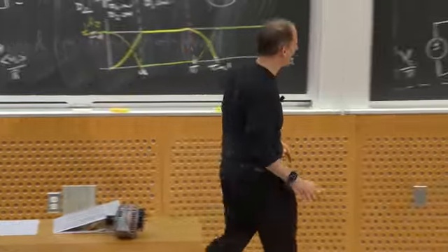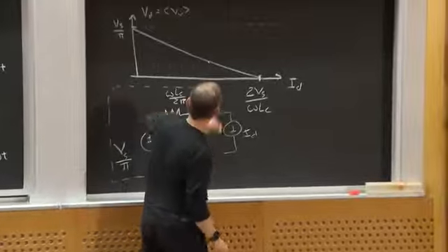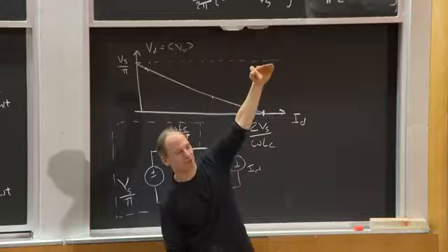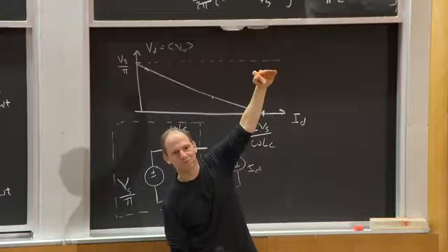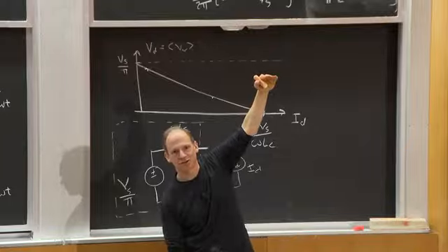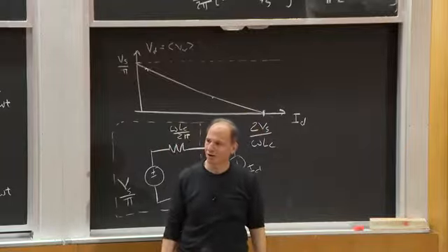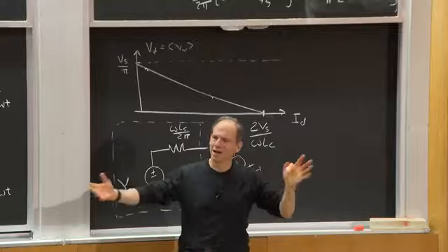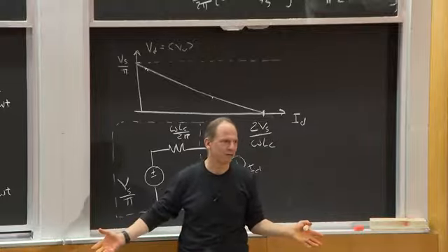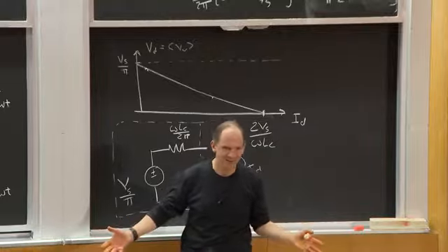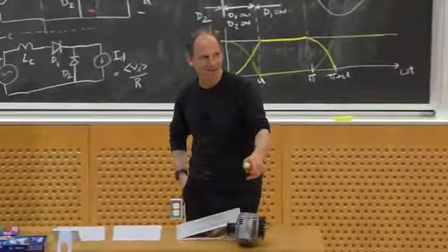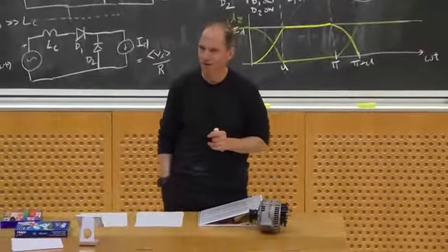Why? Because what happened is you were operating down here, and suddenly the current went away and you went over here, and now you've got this big voltage, and guess what? That big voltage is being slapped across all your electronics. So all the electronics in your car, despite the fact that they're designed for 14 volts, all those modules, every single thing in your car has to be rated for like 80 volts. It's kind of crazy, right? All because of this crummy alternator that has massive amounts of load regulation in it, okay?